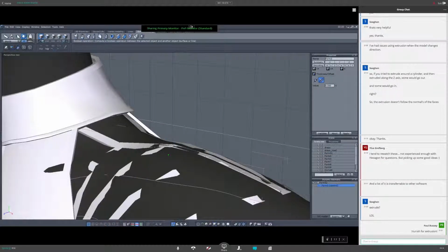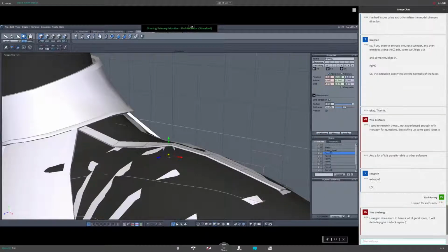You saw something happened. It added thickness to this ribbon, but it went downwards. We want it to go up, and this is what these two little buttons are for. Now I'm going to reverse the direction into which Hexagon will add its thickness. The value here determines how thick your ribbon is going to be. It's a bit too thick for my taste, so I'm adding this lower value. And I think I'm satisfied. Yep, validate, apply.